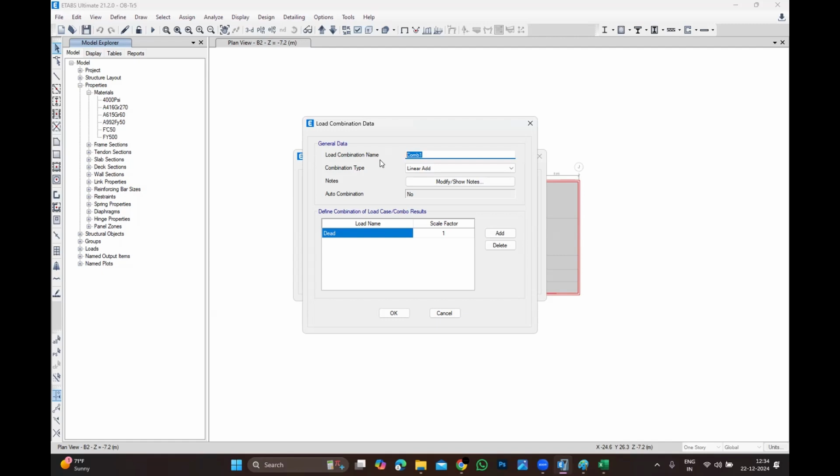Instead of changing the moment of inertia again, what we do is check the drift, displacement, deflection, time period, everything. If it is safe here, then I don't need to create any separate model. But if it fails here, then I will change the modifier and check it. If you only have a 25 to 30% difference it is fine; if it is more than 30%, it definitely fails.